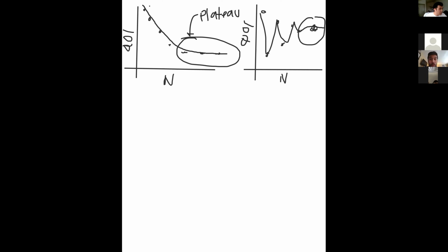Okay. So before we jump into the examples, a lot of times when you're doing these mesh convergence tests, it's going to seem like a lot of busy work because you're just changing a number, running a simulation, which might take a while, and then jotting things down. So it's not the most exciting thing to do, but for many practical applications of finite elements, this mesh convergence is going to be a must.